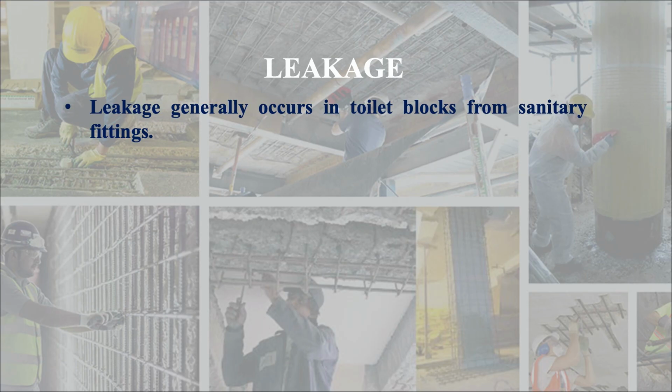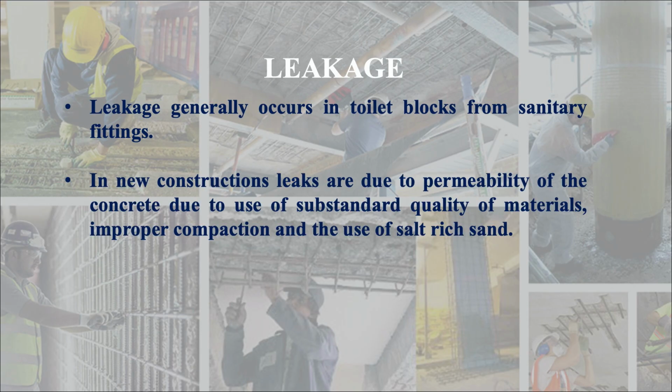Now let us see leakage. Leakage generally occurs in toilet blocks from sanitary fittings. In new constructions, leaks are due to permeability of the concrete due to use of substandard quality of materials, improper compaction and use of salt-rich sand. These are the three factors which contribute to the permeability of concrete.